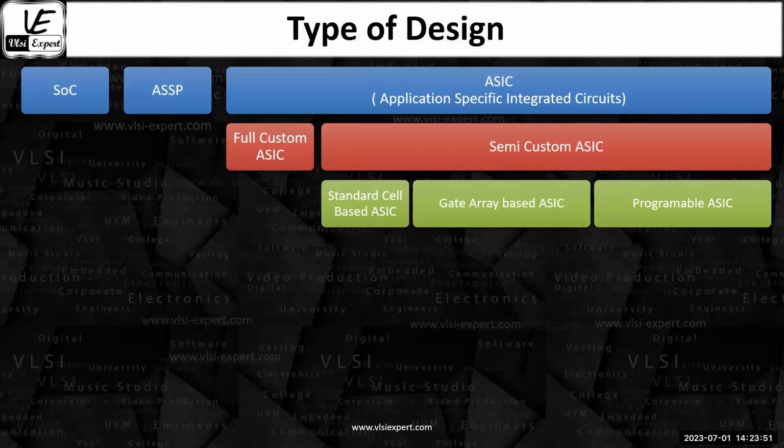I just described it to you. So basically here, all the logic gates, if you are talking about the sequential elements, combinational elements, most of the time these are prepared in advance for each and every technology node. So for each and every technology node, you already have these somewhere, and that somewhere is known as a standard cell library. So that means you will create a set of a library. We will say, okay, for this 40 nanometer, this is a set of a library where I have all the logic gates.